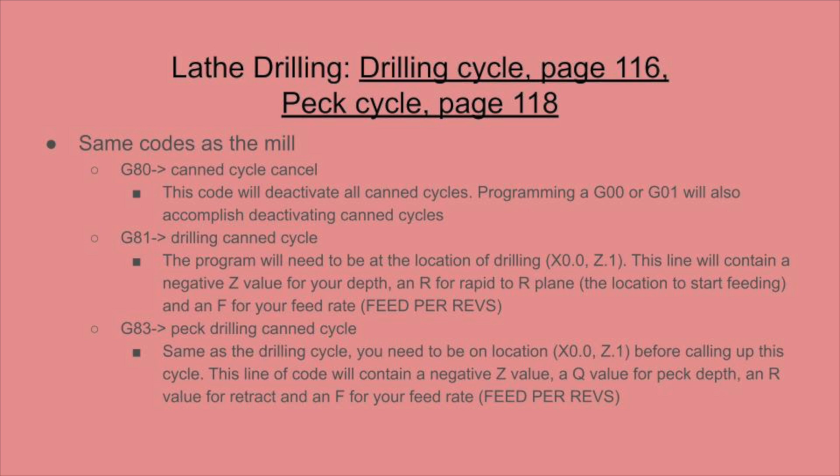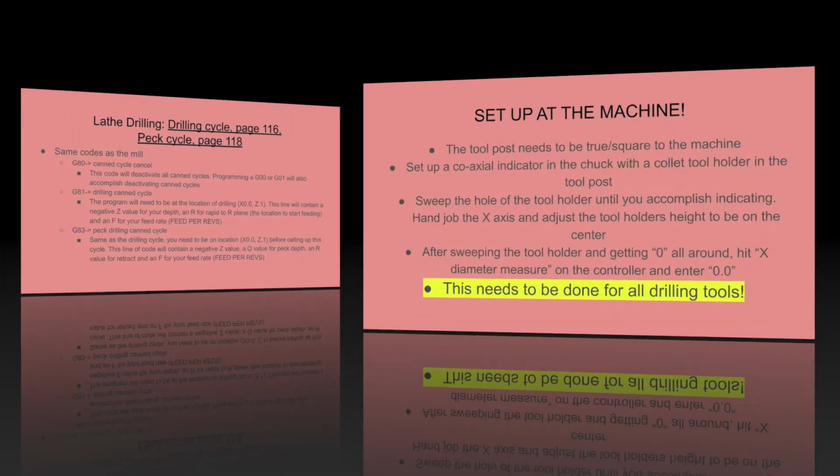We need to make sure that we'll be on location for drilling, which would be X 0.0, and normally about 100 thou in front of the workpiece. The setup of the machine is going to be extremely important.